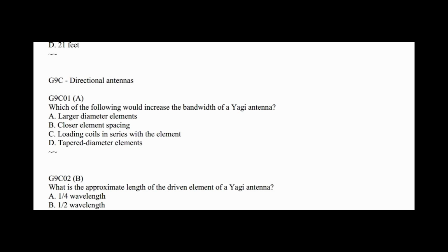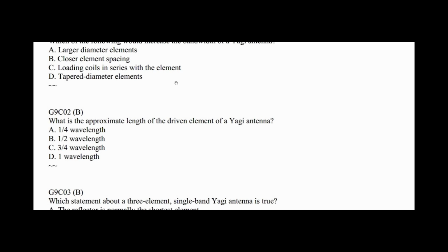G9C01, which of the following would increase the bandwidth of a Yagi antenna? Yeah, larger diameter elements will, and that's true of really pretty much any antenna. Closer spacing, no. Loading coils, no. Tapered elements, no. They'd all have the opposite effect.